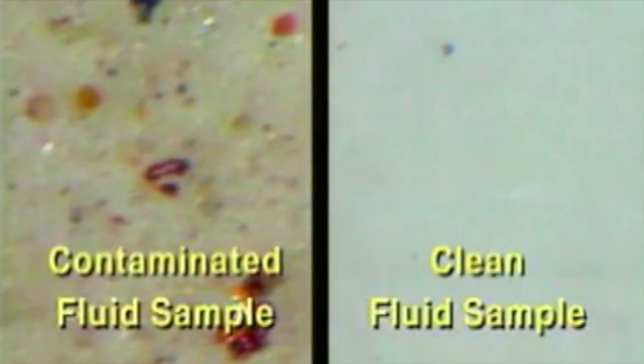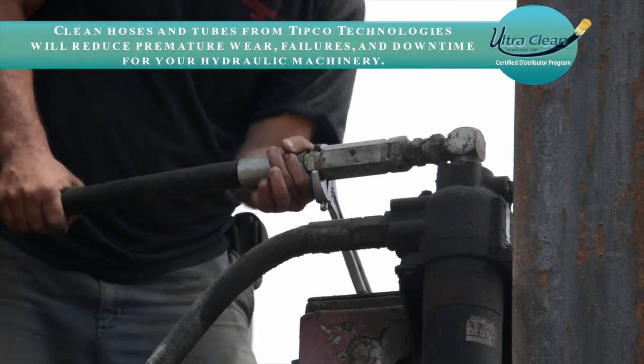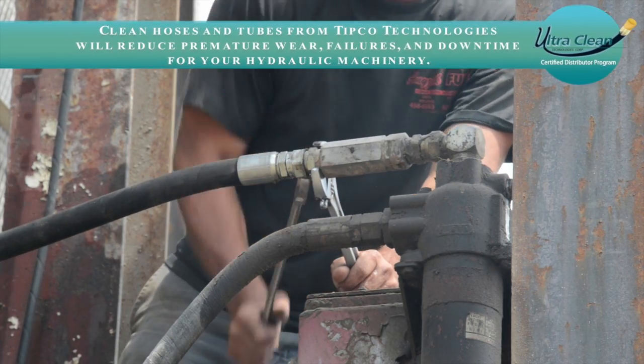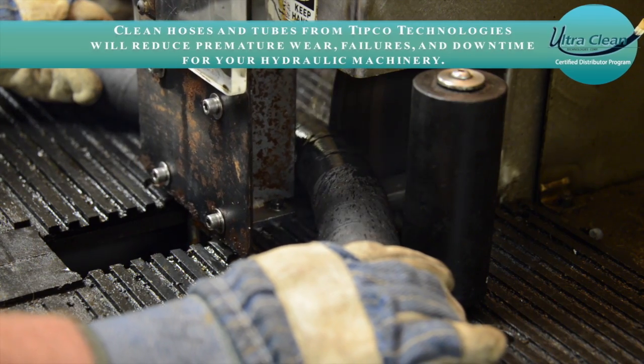Contamination particles look like this in dirty oil. A microscope reveals actual size differences in appearance between dirty oil and clean oil. But where does such contamination come from? It's often there from the very beginning. Large amounts of contamination are introduced at the time of hose and tube installation on hydraulic machinery.